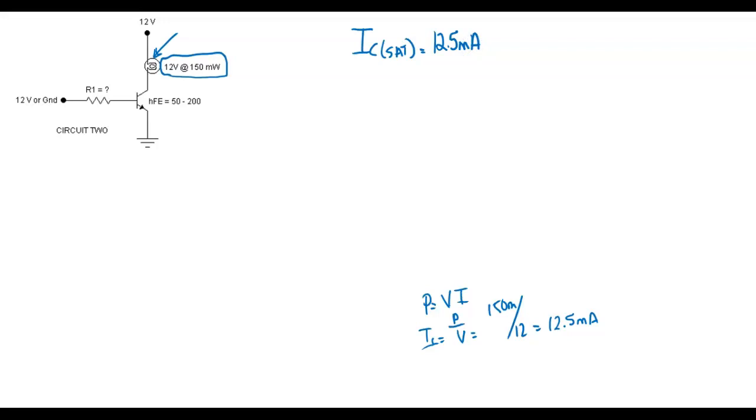And this is what light bulbs are usually rated at. In my house, we don't see them much anymore, but what are light bulbs you put in your house rated at? They're rated in wattage and at a voltage, right? You could calculate the current that thing pulls when you turn it on just by taking watts over volts. And you could calculate the actual current, which you'd need to know if you're going to hook a bunch of lights up to a circuit, right?